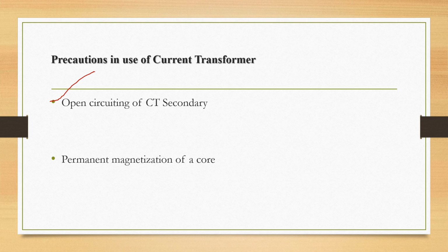Moreover, we can see the high magnetizing forces acting on the core, while secondary conditions tend to magnetize the magnetic material to high values. If the open circuit condition is suddenly removed, the accuracy of the CT may be seriously impaired by the residual magnetism remaining in the core.